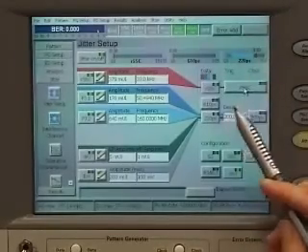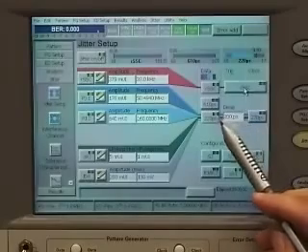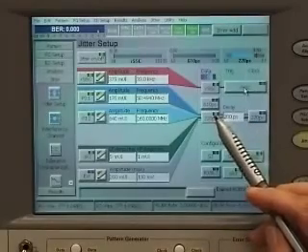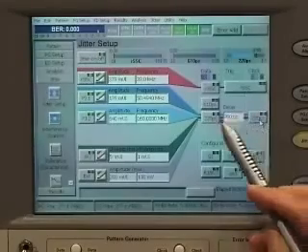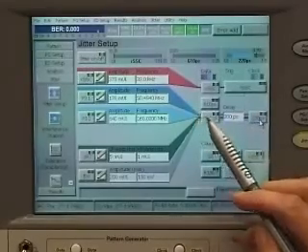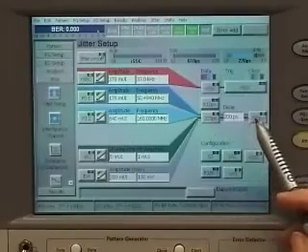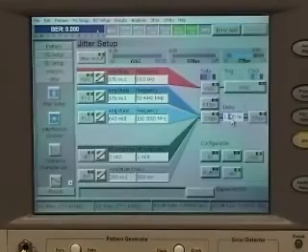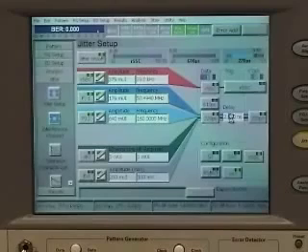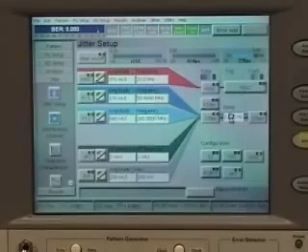This delay describes the phase delay between the jitter on the data signal and the jitter on the clock signal. So if you want to have periodic jitter on both data and clock signals, you can easily change the phase of the jitter between the data and the clock signal.